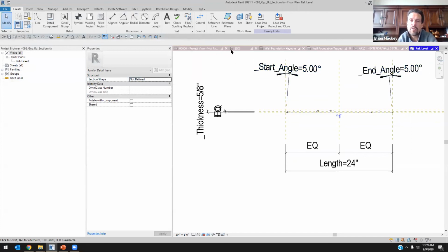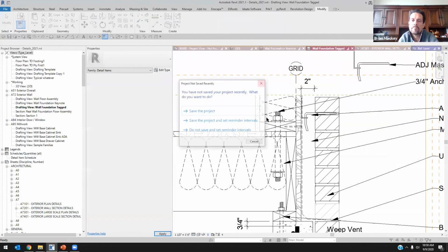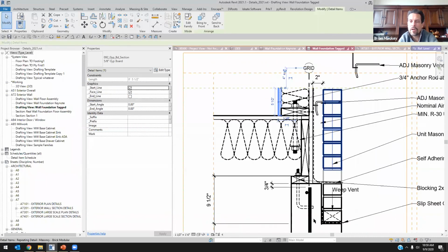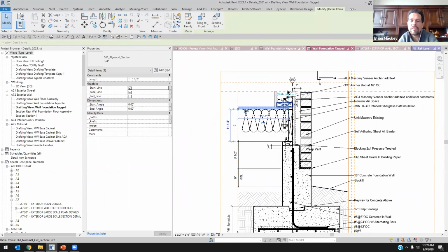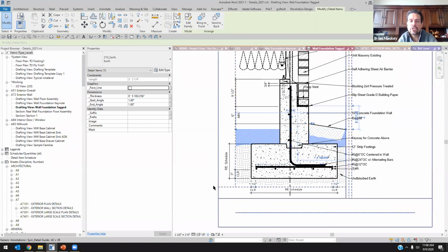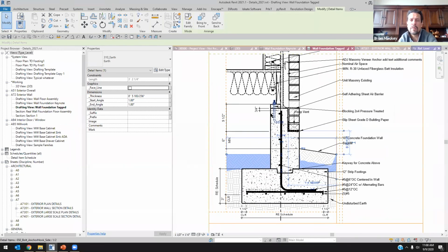So if you go back into the project and we start really looking at what's going on in my project here, I started with my gypsum wall board detail component, and then that got saved as to be my concrete. That got saved as to be my sheathing. That got saved as to be my earth. And then I realized, oh, I want a little squiggly on the earth, so I redid the squiggly. But really quickly, I came through and came in, set this up, went through and grabbed that information. I just kept doing save as, save as, save as. So that one gypsum board detail component became my steel on the sides, my stud on the sides.